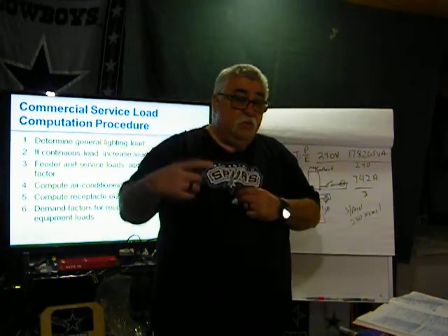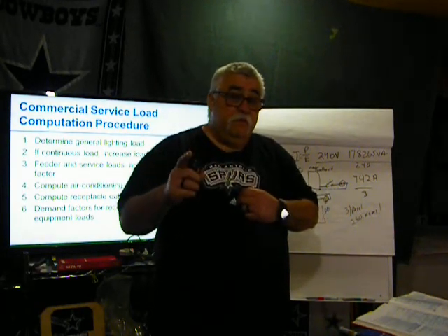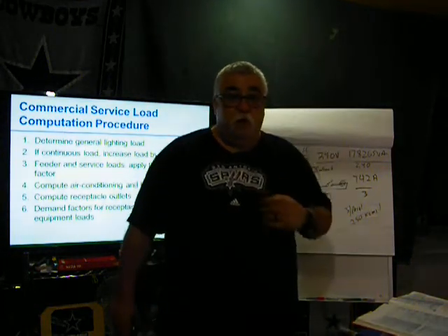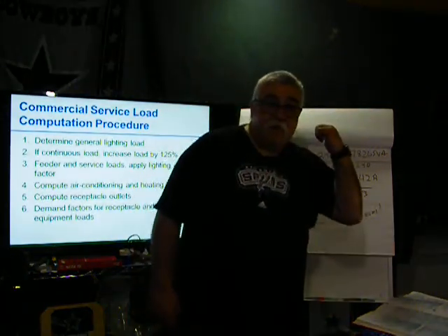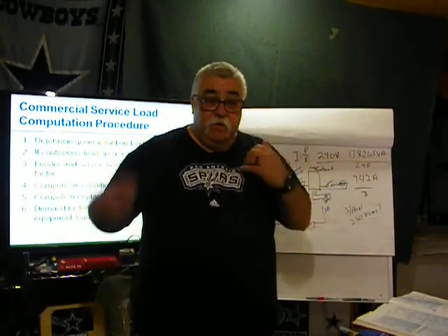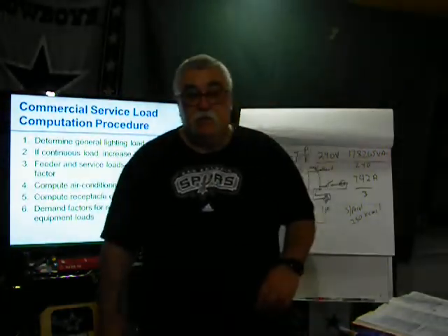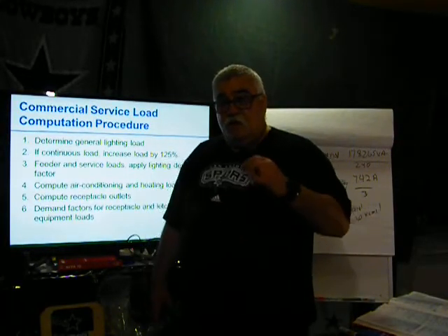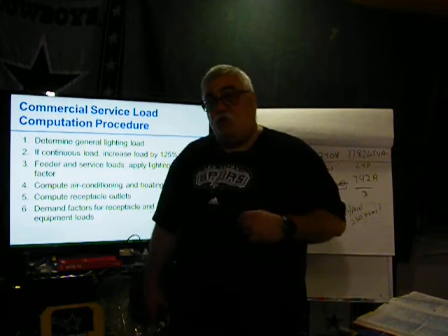And then from there you go to table 250.122 and find me your grounding, because I want you to pull a 4-wire system: 2 hots, neutral, and a ground. We did grounding last chapter, so now we're going to add table 250.122. Find me a grounding wire for whatever amperage you come up to.